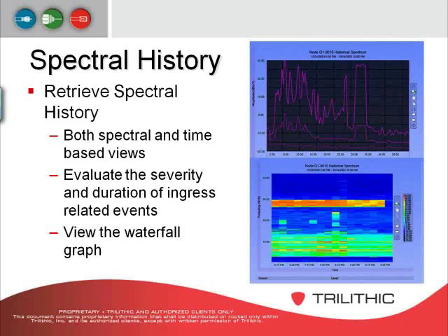Now, if you look towards the bottom where it's around 10 megahertz and around 15 megahertz, there's a lot of color there. So I know I wouldn't want to put an upstream carrier there, because I know that I would have a lot of impairments.